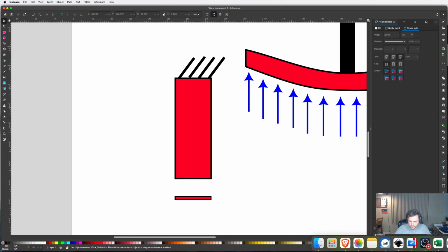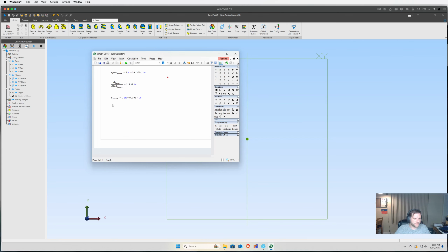And so what we'll then say is that we need the moment of inertia of this thin rectangular beam, and it's going to be 1/12 times the base times the height. So base of the front times the height of the front, actually, 1/12 base times the height of the beam cubed, because there's a cubic relationship with that thickness.